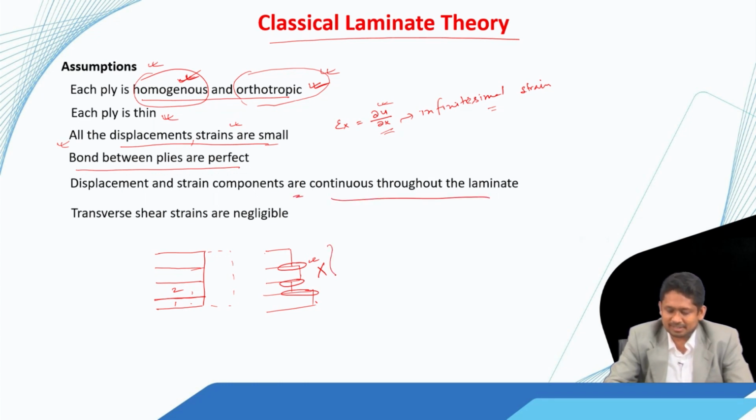We have already seen that the displacements have to be continuous if we do not allow this to happen, and not only that, the strains are also continuous. So, if this is experiencing pure extension, the variation of strain with the length would be this.